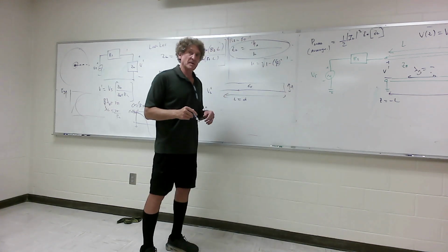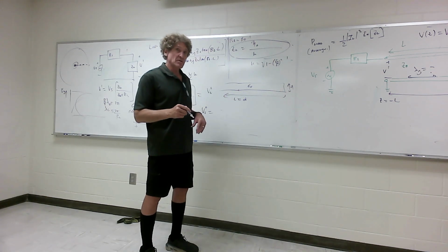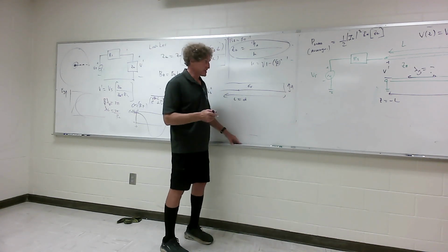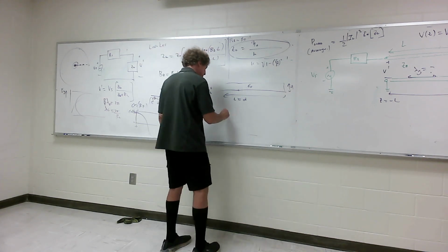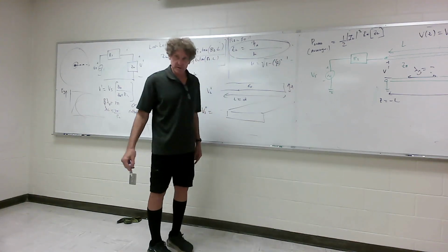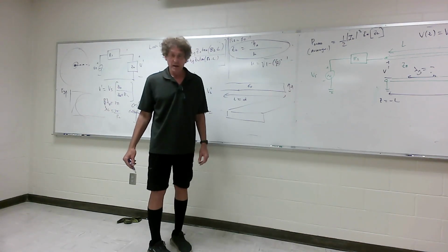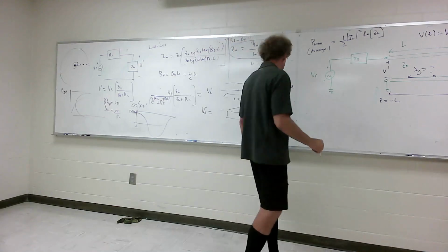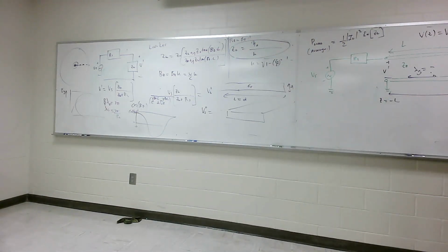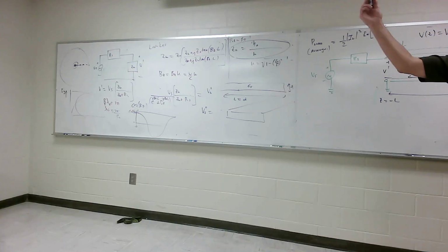Now I'm just prepping you for it. I'm not going to go through it today. When you look at this, and this is maybe hard to see, just think of a very thin piece of material like this that goes on forever in that direction, Z direction, all right? Here's what happens. If you looked at the side of a slab waveguide, and he has the equations, the fields just are like a rectangular waveguide, they bounce up and down.